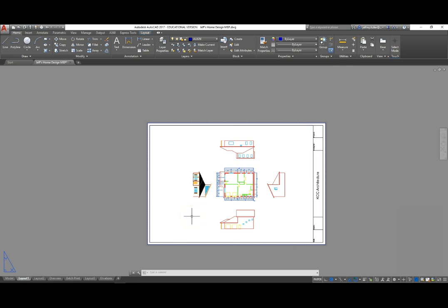One last tip before I go. When placing your floor plan, if your dimensions do not show in paper space, then type the word ANNOALLVISIBLE. And then change the value that pops up in the dynamic input. And of course, that's after you hit the enter button. So change that value, which probably says 0, to 1, and then click enter.